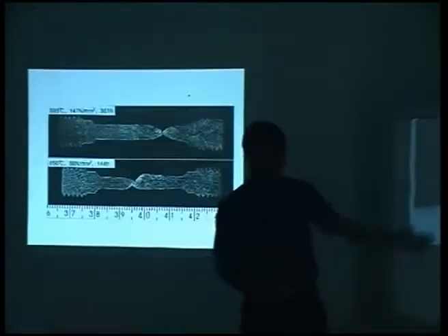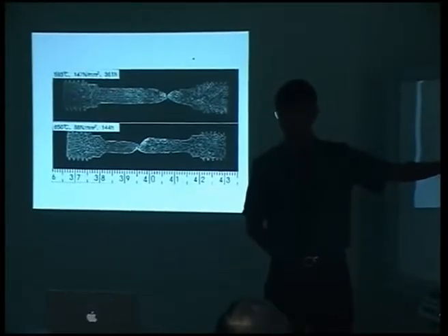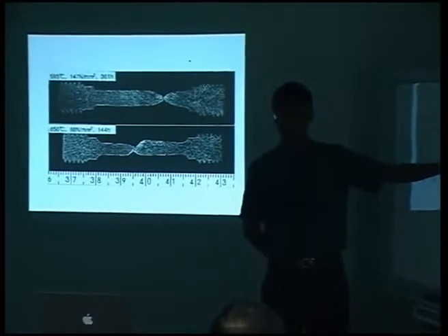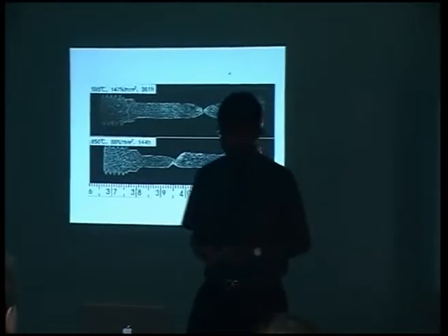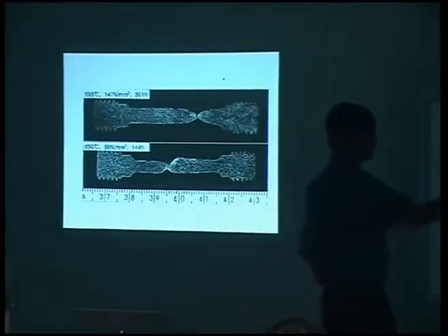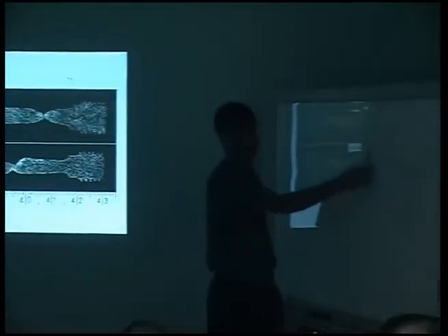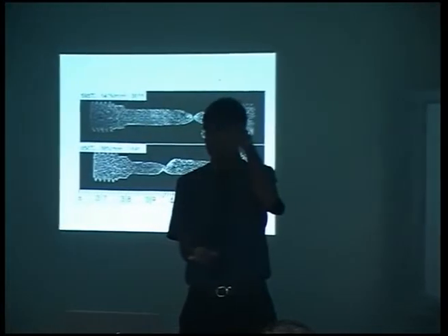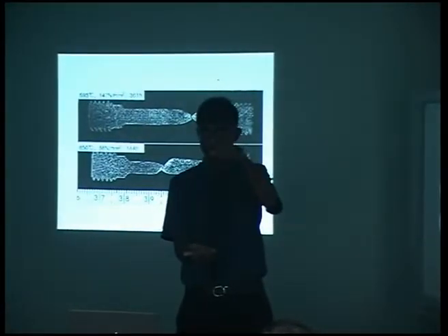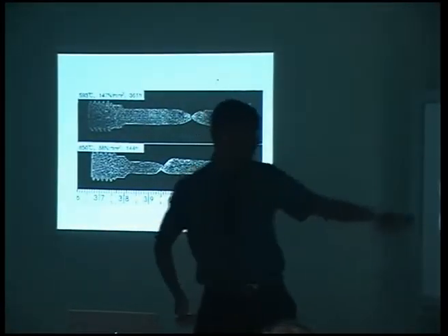Well, we don't know how much strain we are going to concentrate in this region. And the effect of that concentration of strain is to make it fail at a lower stress than if this was just a homogeneous piece of material. Now there are data in the literature in which people have done cross-weld tests and you get type 4 failure, that means over here.